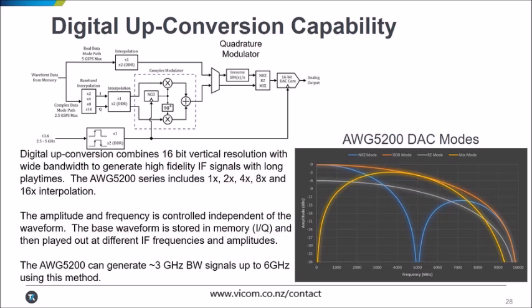The top figure shows a simplified block diagram from the high-speed 16-bit DAC used in each channel of the Tektronix AWG 5200 series, featuring a digital complex modulator and multi-rate interpolation. With this internal IQ modulation feature, you remove the IQ mismatches that are attributed to external modulators and mixers.